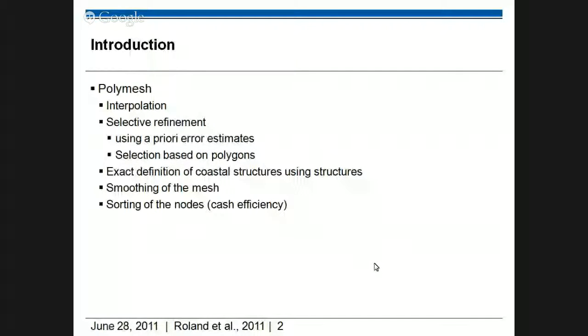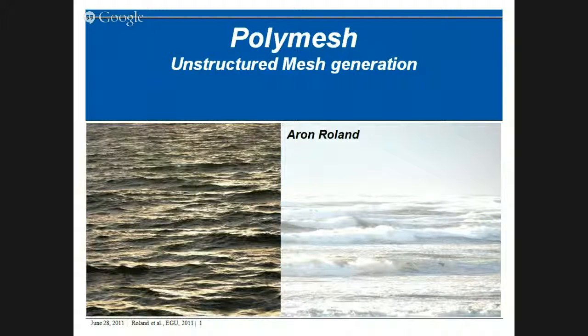It really depends what you want. If you want to know the waves all along the islands, you use all the islands. If you don't care about the waves on the islands, it's just blocking for you, then use the regular gradient obstructions. But we don't do obstructions with the triangle mesh. In that case, we pretty much resolve all the islands we can, and of course there are some small islands that we give up or just merge together.